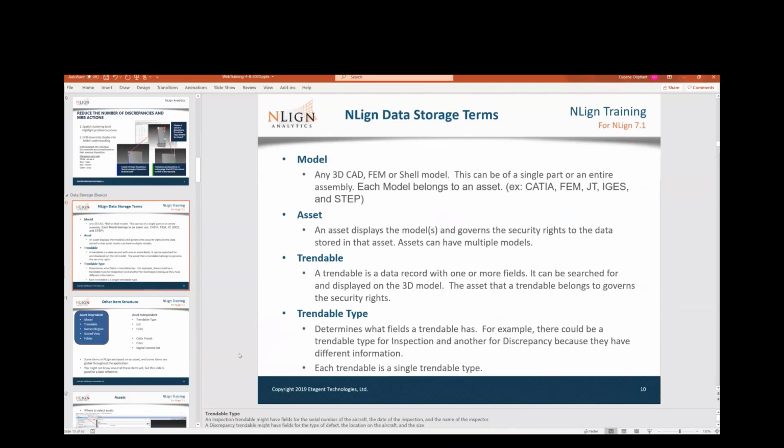So you could treat that piece of paper as a photograph of the part, as long as that printout on that piece of paper was to scale. What I would suggest, if you have some legacy data, that's probably the only way you can do that. Perhaps the aircraft is left, or the part is no longer around, and you can't find it to get a picture of it. So as long as that was to scale, you could do some actual damage mapping with that. You can overlay that picture of the piece of paper, or that scan of the piece of paper, onto the model, and then highlight the area that was circled on the paper as the damage area.